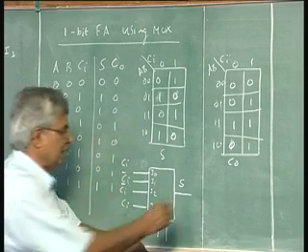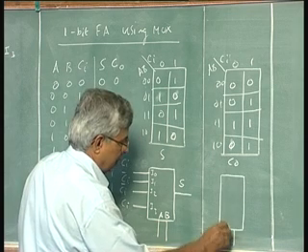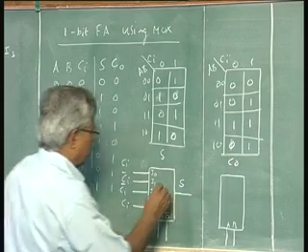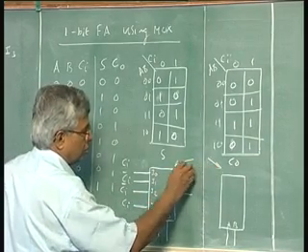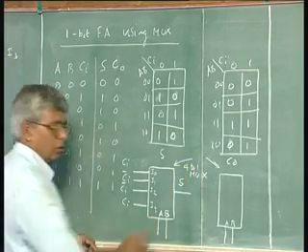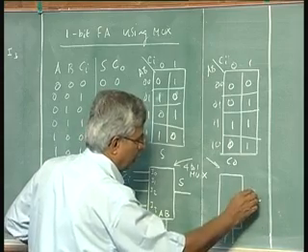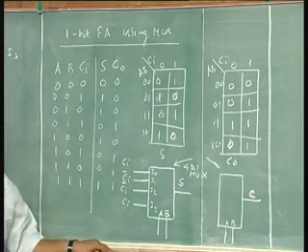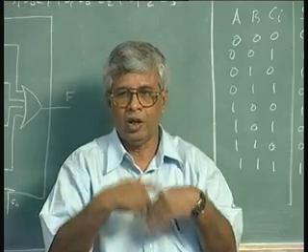Coming to the carry, again there are 4 inputs, so I will use A, B as the selectors, and this mux is a 4 to 1 mux. This and this are 4 to 1 muxes. Now, in this output I will get carry from this map, I will do this. So, I am now mapping onto this given hardware, namely 4 to 1 multiplexer, a hardware mapping, not mapping like drawing, the hardware mapping.